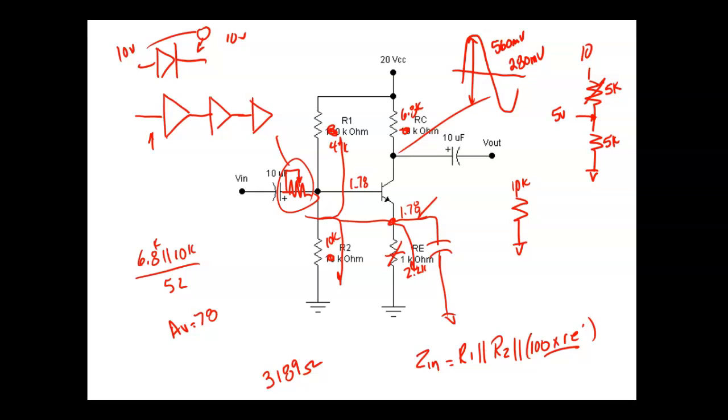But I still have a connection to the top of that capacitor. So I measured 1.78 volts right here. Notice it went up some because we lost this resistance. And I measured 1.78 volts right there. Two things could cause that. The base to emitter could be a short. It could be shorted, which we have that happen. But we know that's not the fault. So I could come over here and put a piece of wire and it would do exactly the same thing, because it's not dropping any voltage. But here we know the problem we're putting into it. We're not trying to troubleshoot.